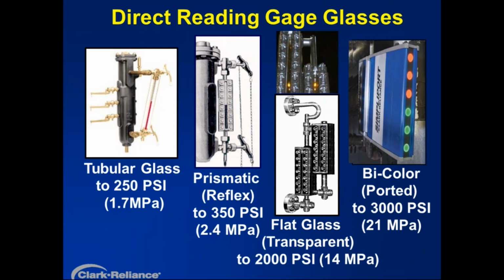When the prisms are backed up with water up to the water line, what you're actually seeing there, and why the water looks black, is you are seeing directly into the back of the gauge. And the back side of the gauge is solid metal. In this case, it's either cast iron or carbon steel. So because you're just looking into the back of the gauge, that's why the water level looks black, even though we all know that water is clear.